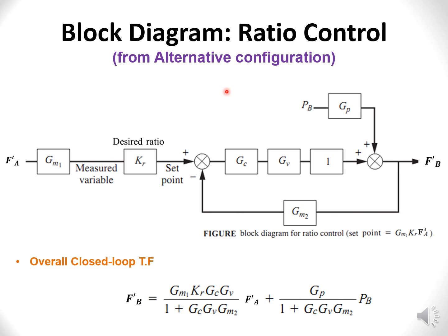Whether this controller or an advanced controller, any method for controller that we're going to use, we have to take this into consideration to make sure that the controller can work properly under set point change and disturbance. We cannot have a different set of tuning for set point and a different set for disturbance.